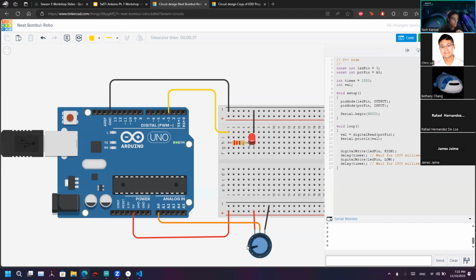But if you change this value to a random pivot point, now we'll see it change to 1. Sorry, digital read. It should be analog read. Yes, I was like, wait, yeah. Good catch. Analog read. Let's do that right here. But you see, it was going from 0 to 1 because it was reading digitally, since you can use analog pins as digital readers and writers as well. If you use analog and start this, now you'll see 941 instead of what we saw earlier.